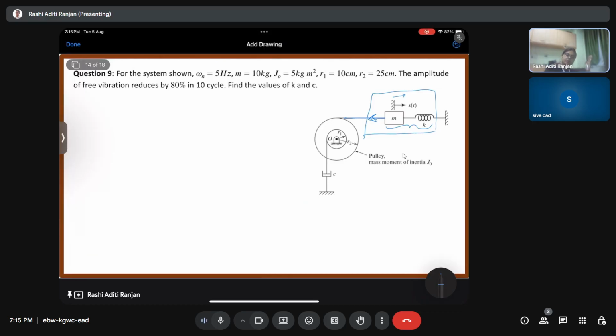How is the force getting balanced, right? The mass is moving in this direction, which means that its acceleration is in this direction. However, the inertia of the body is going to be in the opposite direction, right? So essentially, what are we going to get? We are going to get P plus m x double dot plus k x is equal to nothing but 0, right? From this we get P, which is the tension, is minus of this. For now, we'll keep it like this.